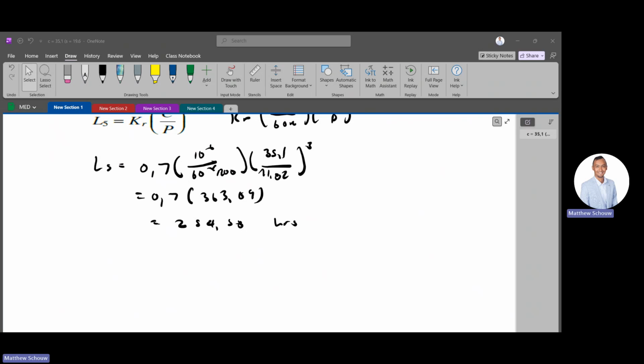And they do state here that to improve the reliability of this pairing from 90 to 94%, a reduction of median life of 1820 to 1275 hours is required. So you can have a look at that, but what's key there is that you have to change that median life hours. Kind of makes sense in a way.